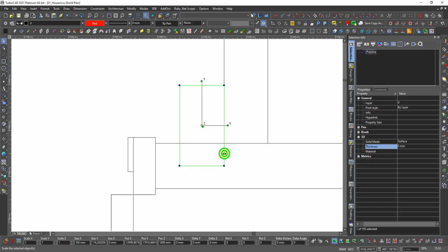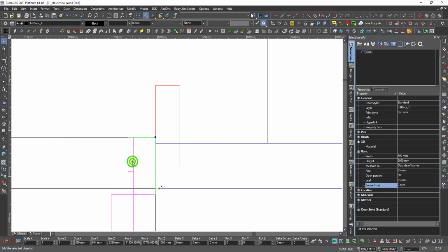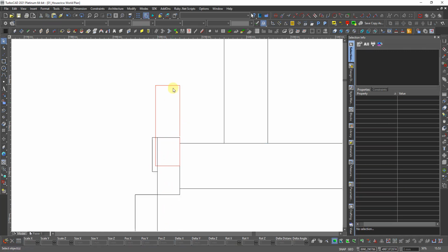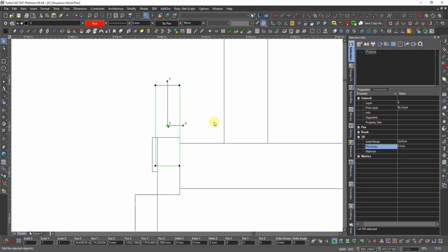Then I take this edge and drag it over to nearest here. That is the exact measurement I need, standing down here now in size X. So I go there and I Control C, copy it, and then I go to the door and I want to move it, Control V and enter. Now you see this meets correctly. So that is the other way to do it.